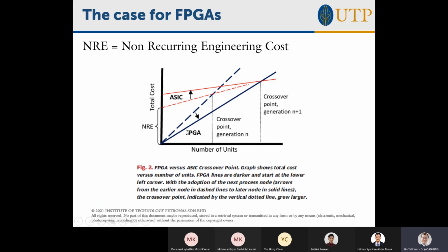So that's the attraction of FPGA at the initial point: the cost to get a programmable, customized hardware circuit that you can actually use is much cheaper for FPGA than for ASIC. Whereas for ASIC, you need to get volume first, then it makes sense to work on it. So it provides a low entry point.